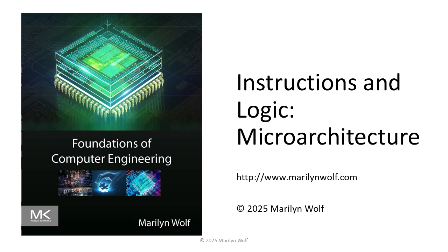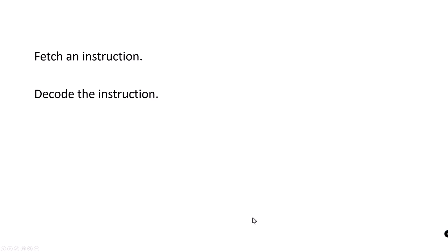We can use the Datapath controller approach to design the microarchitecture for a CPU. CPUs repeatedly perform a fetch, decode, execute. They fetch the next instruction from memory. They decode the instruction to determine what operation it describes. They execute the instruction to perform the operation.